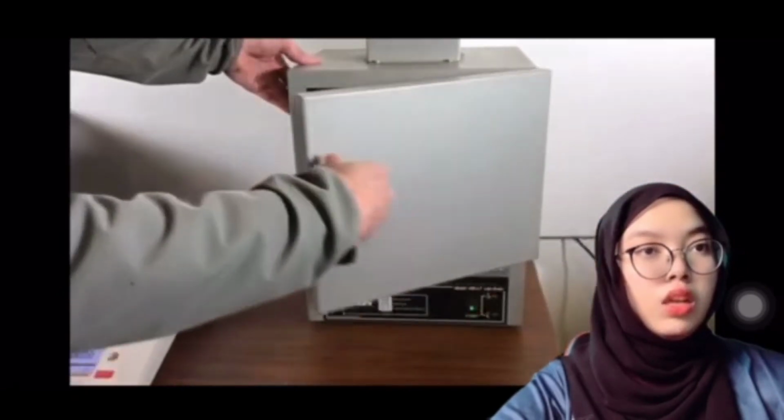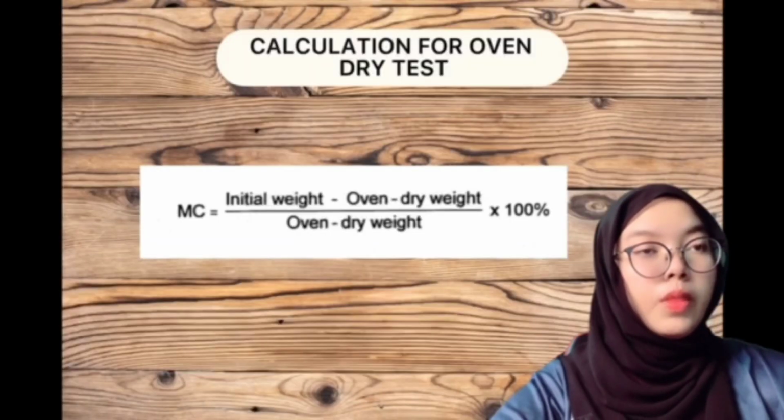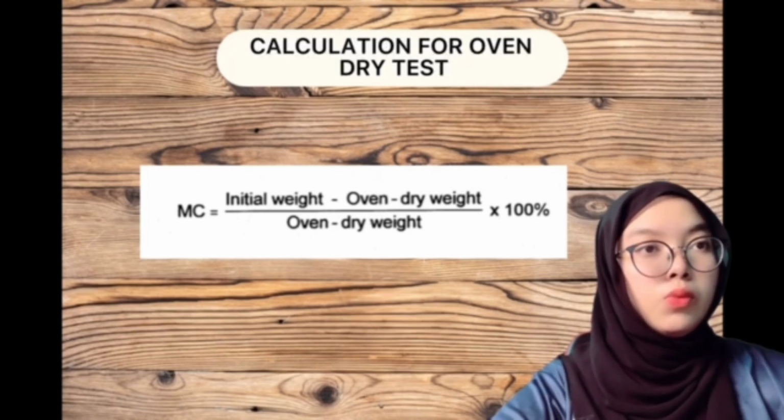In the solid wood products industry, the most often used moisture content is defined on a dry basis. This means that the moisture content is defined as MC equals initial weight minus oven dry weight, divided by oven dry weight, times 100%.